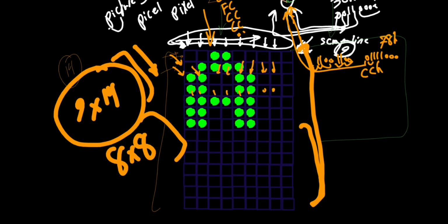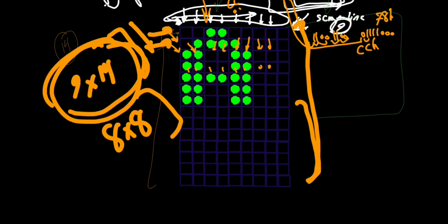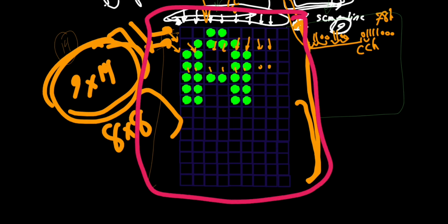The horizontal resolution of our display is 9 pixels. The vertical resolution is 14. The overall resolution is 9 by 14. And we would have these scan lines as we explained. And another last abstraction is that we call all this, what we said is one character box, one character row. We say we have one character row currently, which has 14 scan lines capable of saving one character. So these are different abstractions, and you will understand later why we are defining abstractions this way.